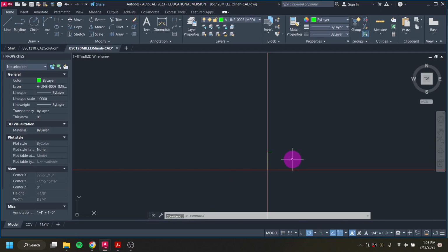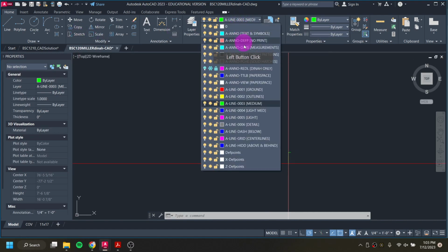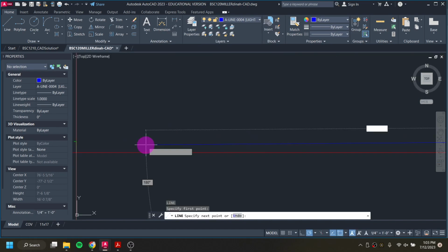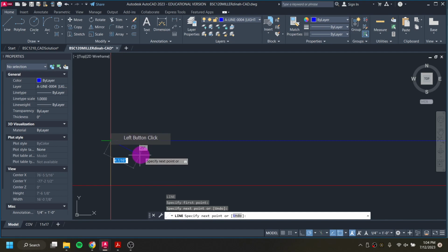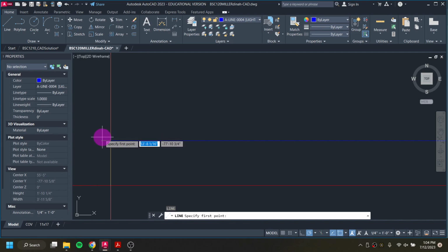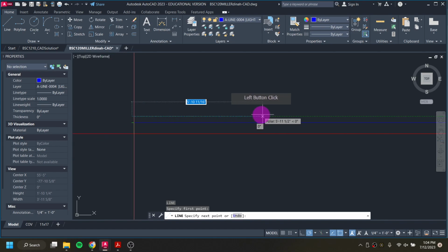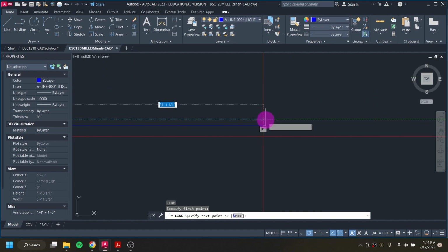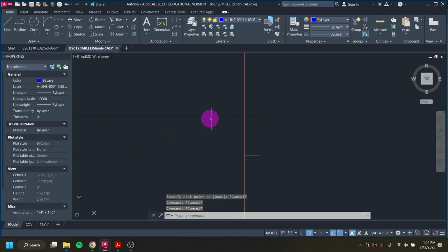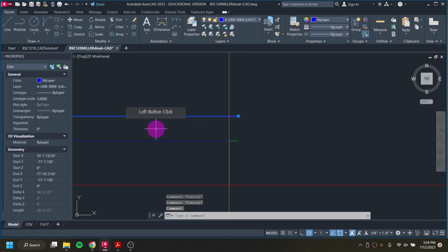If I go back into AutoCAD, what I would typically do with how I have everything set up is I would go into my line 4, the light medium, and I would draw a line just across from here to here. If I had drawn it all as one line though, so I hit escape to end the command, I'll hit enter to go back into it. If I had just a line that went all the way across here, and I wanted to make it into 2 different layers, I do have the ability to switch parts of it out by using the break command.